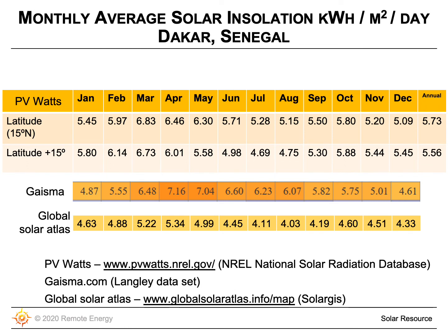So we're actually looking at a collector. We could say that if this was a PV module, it would be tilted up at the angle of the latitude of the site. So Dakar, Senegal has a latitude of 15 degrees. In this case, we are measuring the solar irradiance from a collector that is angled at 15 degrees. Essentially, we are collecting that solar irradiance at a right angle, which would give us a higher value than if we collected it from a horizontal or a flat angle.